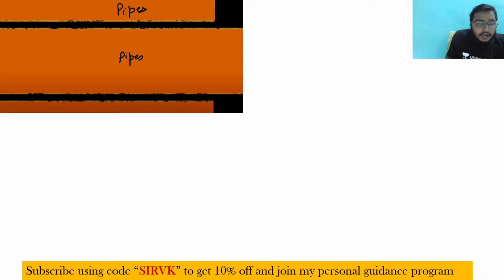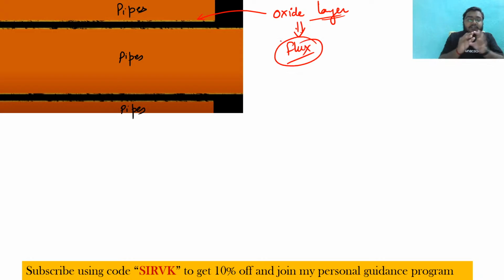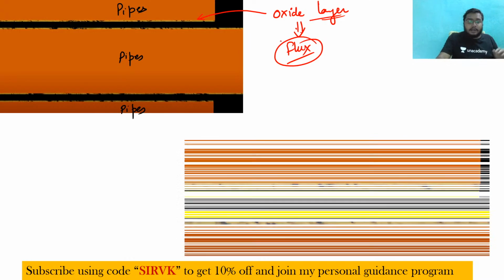Suppose these are the pipes, and you want to join them. Before joining, you can understand that here, what is this? Is it flux? Just let me change the color. What is this? Is it an oxide layer? See, the oxide layer is on the surfaces of the pipe, so we cannot join it, and hence we require the flux. What is the use of the flux? This flux basically has some acidic things in it. What is happening? The oxide layer is removed clearly like this.